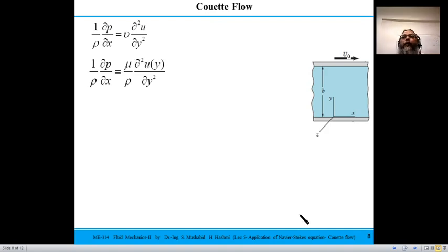We have rearranged this equation in such a manner so that we can integrate it to get the velocity profile, because the objective of solving the equation is to get the velocity profile. I have rewritten this term onto the left hand side and this term onto the right hand side because rho and rho cancel out, so you only end up with mu on the denominator of the left hand side. So that is what has come here.